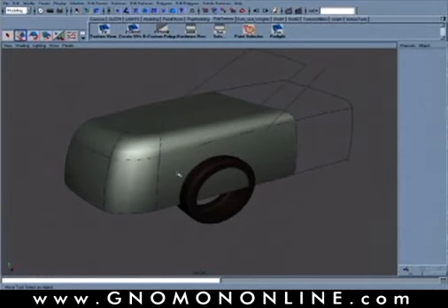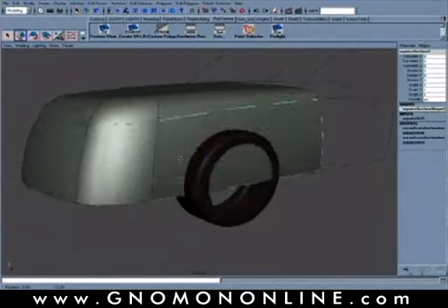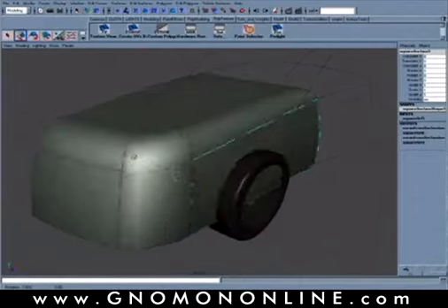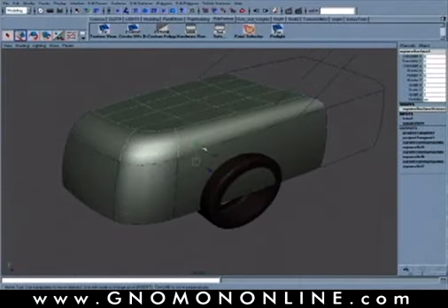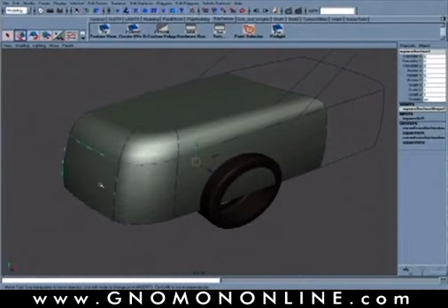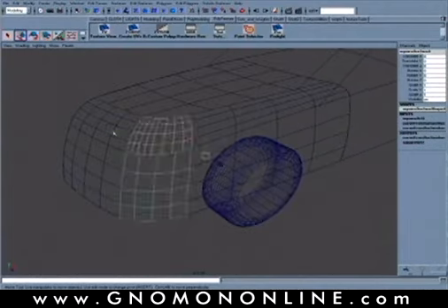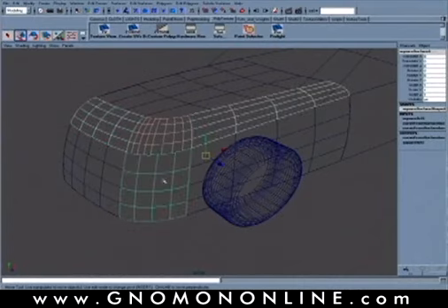What I have here is a model where each one of these panels has been created as a square surface, so defining this in terms of four-sided boundaries. Okay, building it in order so that the top surface and the side and the front are all created first, and then the radius or the connecting surfaces are all built secondary. Okay, so these are built afterwards and then trimmed out part of that.